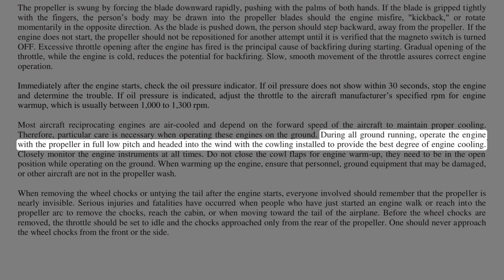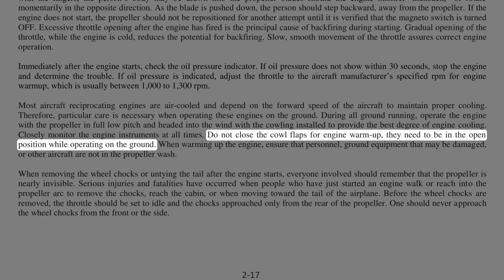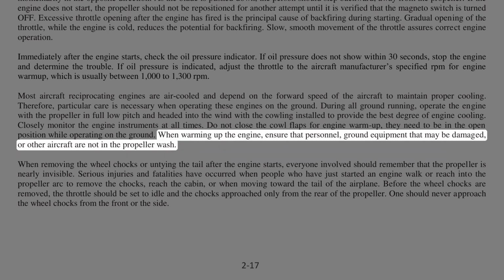During all ground running, operate the engine with the propeller in full low pitch and head it into the wind with the cowling installed to provide the best degree of engine cooling. Closely monitor the engine instruments at all times. Do not close the cowl flaps for engine warm-up; they need to be in the open position while operating on the ground. When warming up the engine, ensure that personnel, ground equipment that may be damaged, or other aircraft are not in the propeller wash.